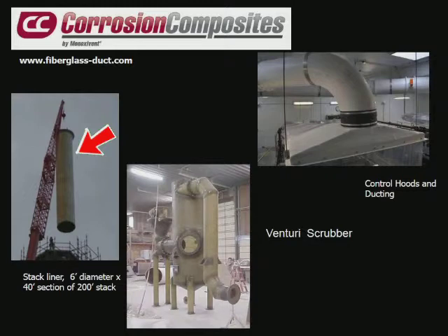When they did that, the old brick and concrete couldn't take the sulfur condensate that would occur in the stack. So we built these liners that would drop in, and the lower section had a base that anchored, and then the next sections had a big funnel with an 8-inch socket. So the sections dropped in place, and then the very last section on top only went halfway into the socket, and that flange that you see at the top of it sat on the concrete. This allowed for expansion and contraction, and with the system the way it was, it required no internal fiberglass joints. That stack, the first one, was installed in a 4-hour period. So we were quite amazed at that.